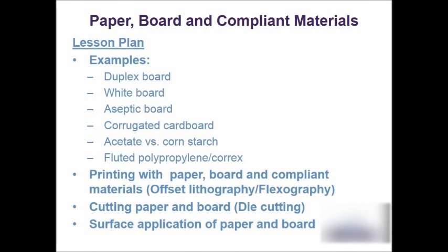We normally print on duplex board using a process called offset lithography. And sometimes the board is also laminated on the outside to make sure that it retains a high quality finish. Now, because this board is only for a single use, so you would only need to use it until the item inside is finished, that means that it's normally quite lightweight, so the GSM would be quite low because it doesn't need to be particularly thick. That's because the packaging only needs to protect it for a certain amount of time.